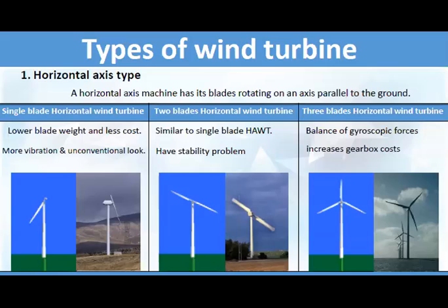While permanent magnet direct drive generators can be more costly due to the rare earth materials required, these gearless turbines are sometimes preferred over gearbox generators because they eliminate the gear speed increaser, which is susceptible to significant accumulated fatigue, torque loading and related reliability issues. Maintenance costs are also less. There is also a pseudo direct drive mechanism which has some advantages over the permanent magnet drive mechanism.